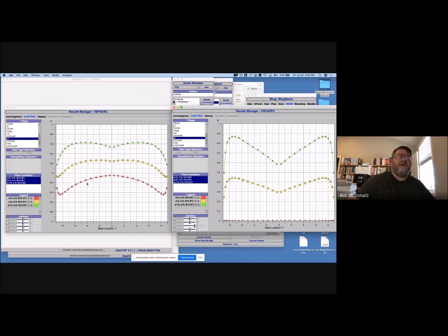So you don't necessarily want to, in aerodynamics, compare angle of attack to angle of attack. That's the first rule. You don't care what the angle of attack is. The angle of attack is just, you know, somebody walked down the side of an airplane with a paintbrush and drew a reference line. And the physics don't care about your reference line. The physics don't care about angle of attack. The physics care about lift coefficient. They care about stall, and they care about drag coefficient. So when you compare two drags, you want to compare them at the same lift coefficient. And in this case, what we're seeing here is this airplane on the right with no twist.